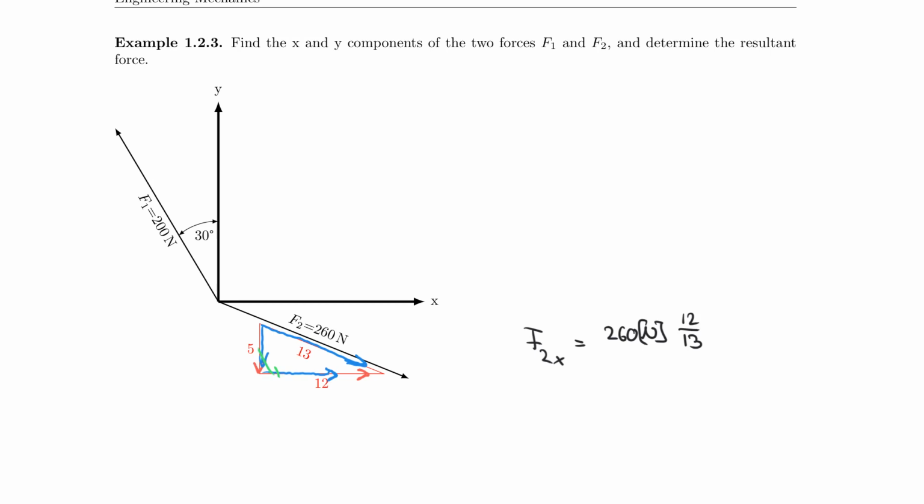So yeah, stay away from that, please. That is something that can go wrong. Then another thing that I need to point out here that is very important as you move on through the lecture is that this 30 degrees is often used for students to find the y component. So the way they calculate this is by saying that F1x is actually equal to 200 times sine 30,